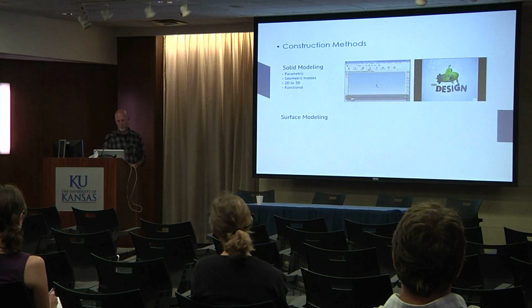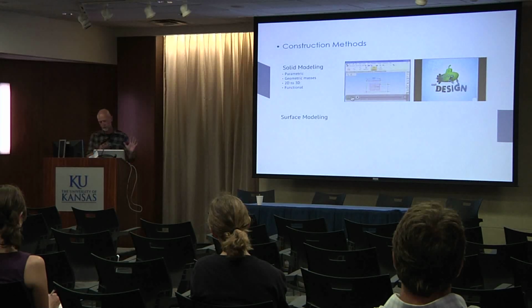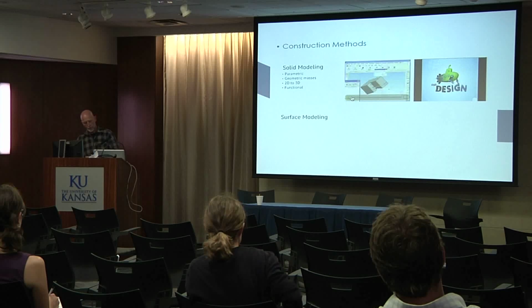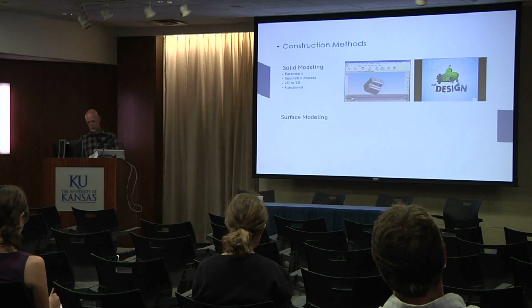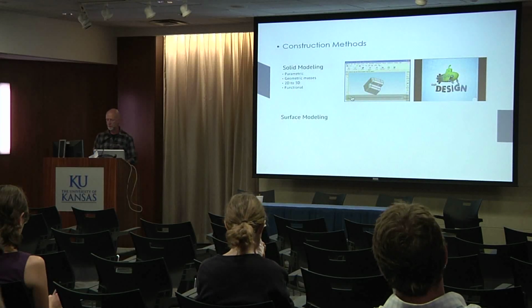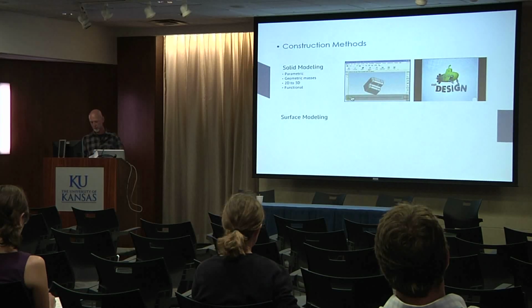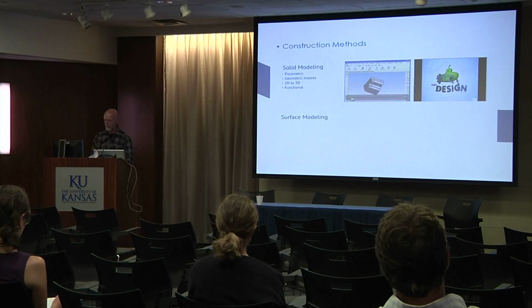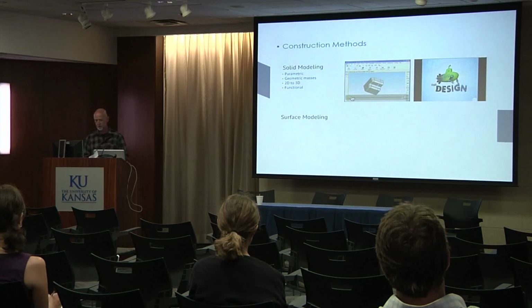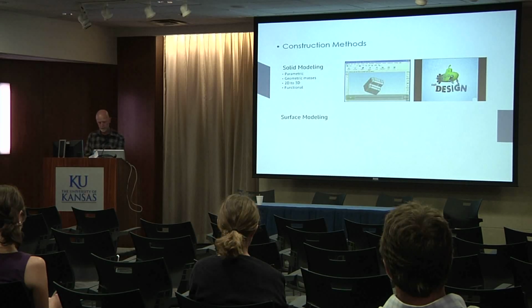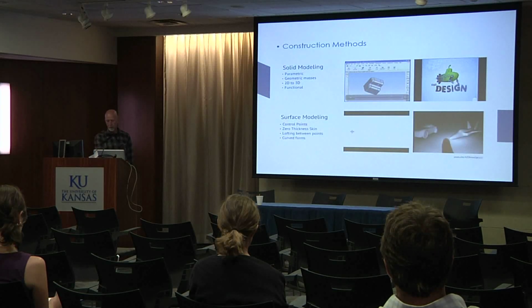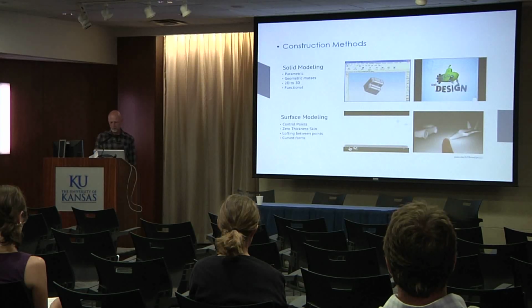So this is the SolidWorks interface, which I'm just going to talk through if you just watch that. In a solid modelling system, objects are defined as geometric masses that are typically created by extruding a 2-dimensional sketch along a third axis. Solid modelling tends to be parametric, meaning that it is dimension driven with parent-child relationships. Dimensions can be numerically input as well as derived from other dimensions. Solid modelling tends to be more concerned with function rather than aesthetic design, and is typically used by engineers. This is rather short on here, sorry.